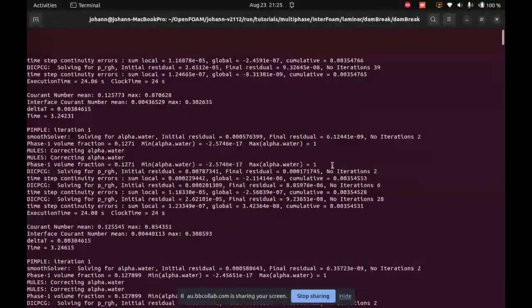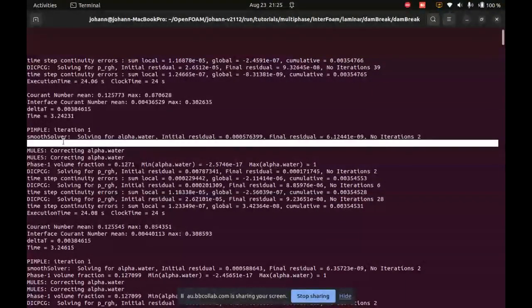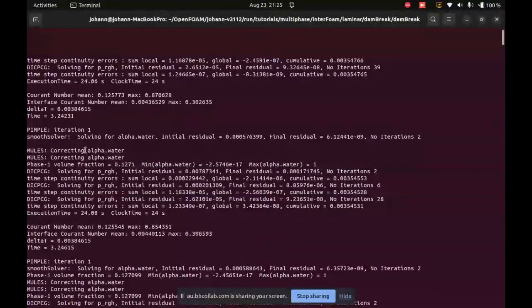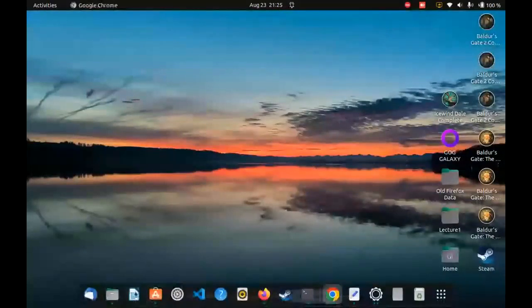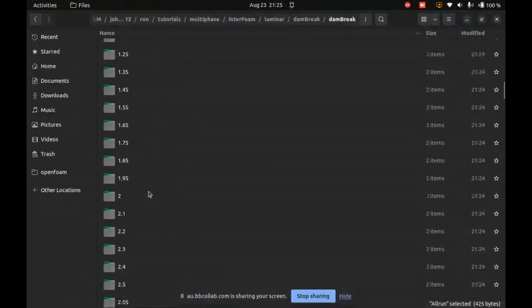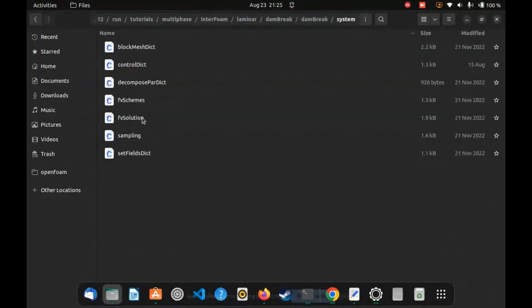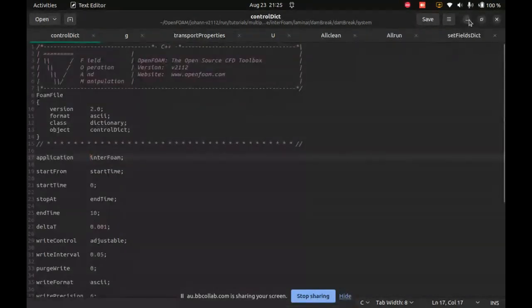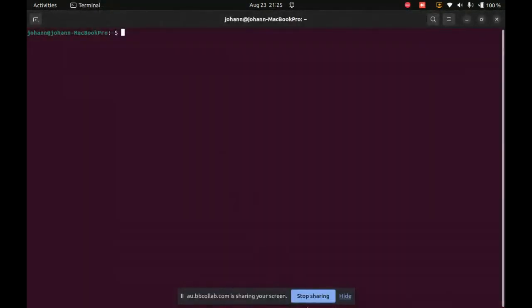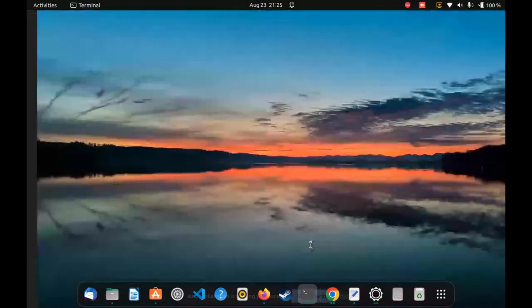But just know that if you want to use a different kind of solver, so instead of a Gauss-Seidel solver, you want to use a Jacobi solver, you could implement that in OpenFOAM, and OpenFOAM has it. You could say, well, I don't like this, so let us go into the system and change the solution. I'm not comfortable with the symmetric Gauss-Seidel. I'd rather have a Gauss-Seidel or a Jacobi or a PCG, whatever, right? But as you can see, it's solving pretty quickly and it's almost done. Well, it should be done already. I've talked enough.